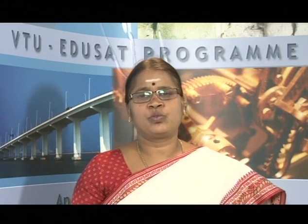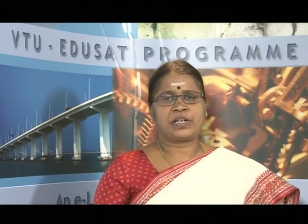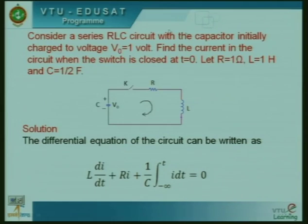Later on we will move to a concept called transformed network. To start with, let us consider a simple network. It is a series RLC circuit, and the capacitor is initially charged to a voltage V at 0 minus given by 1 volt, and our aim is to find the current in the circuit when the switch is closed at t is equal to 0.